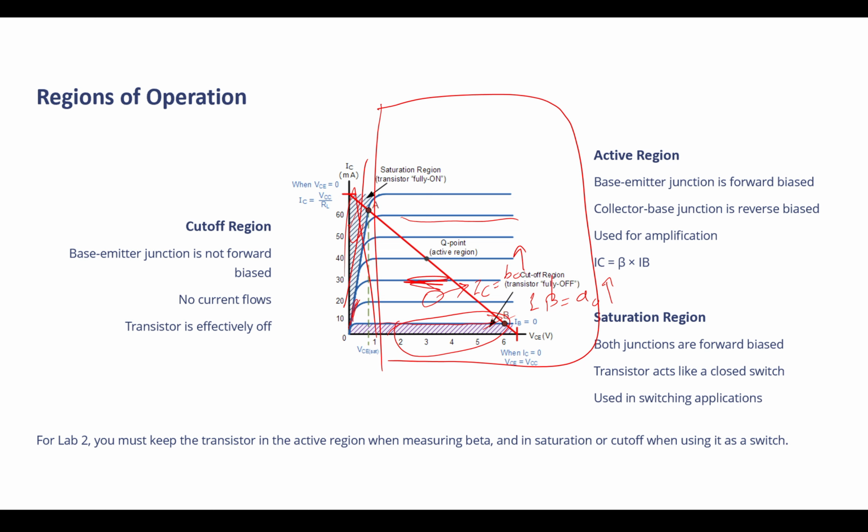So this behavior basically gives us the ability to say screw Ohm's law. Now Ohm's law doesn't affect your current. It doesn't matter what the voltage or KVL of your system is when you have a BJT. The current passing through the collector is defined based on the current of the base.